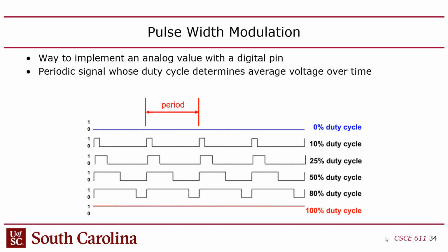And the same thing goes for a power electronics circuit. Like when you hit the gas on your Tesla, it's sending a PWM signal to the electric motors, or to the converter that's sending the power to the motors, right? Because the power electronics are expecting an on or off, because they're generally based on a switching converter, like an H-bridge circuit, right? But then there are other cases where you may want to use an actual analog signal, like if you're looking for high fidelity audio, for instance. Does that make sense? All right.